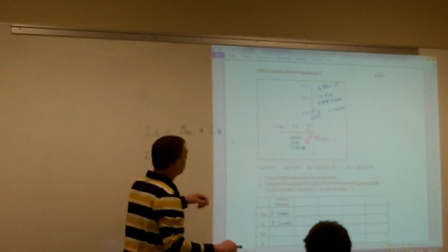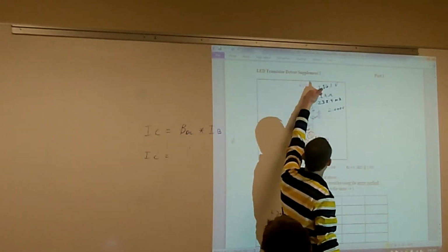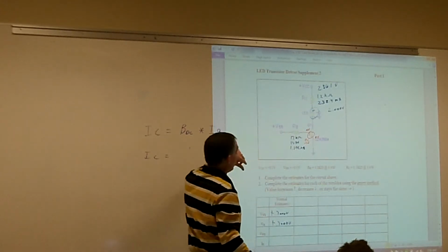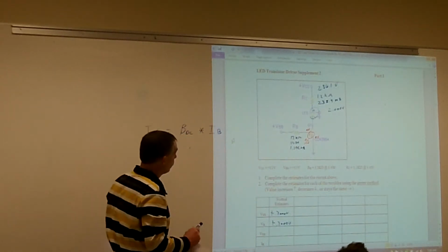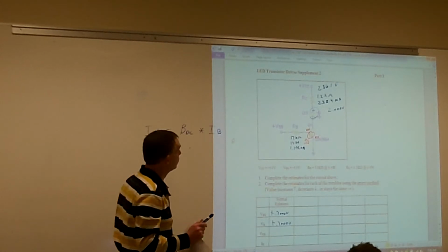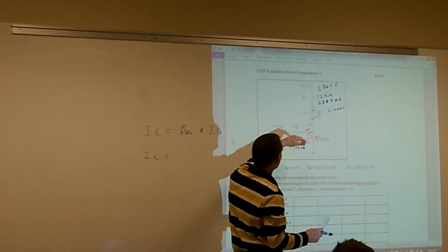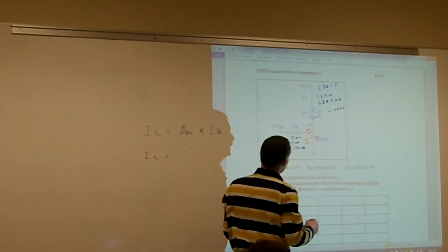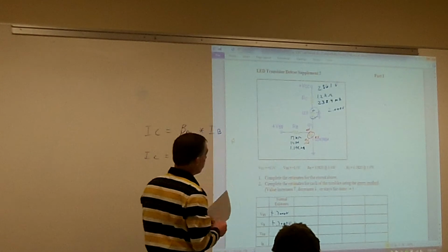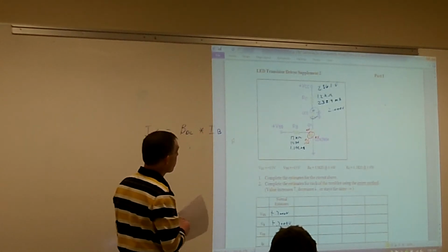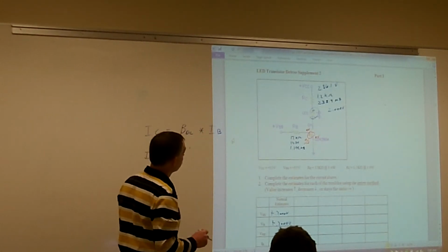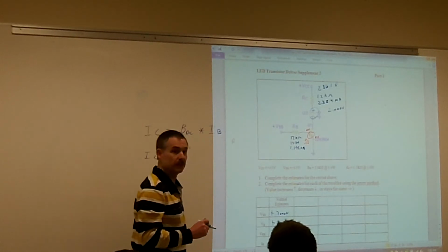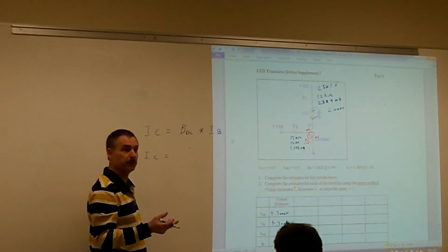Remember from the lecture from the last time, if we end up getting a large voltage across our collector that's more than our source voltage, what's that telling us about our... Yeah, we're in saturation. And we know that we can't get any more voltage than what our VCC is. So if we're in saturation, then what's my voltage drop going to be across C to E then? 0. Approximately 0, but otherwise we use approximately 0.2 volts.